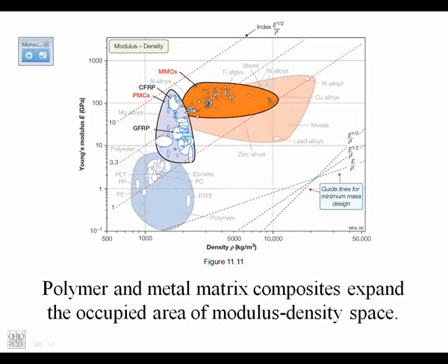So here we have Young's modulus and density. And so this is obviously an important consideration. These are two properties that are important for things where we want something to be stiff and light at the same time. That's going to happen in situations like the outside skin of the airplane, or panels or I-beams that we need for light buildings.